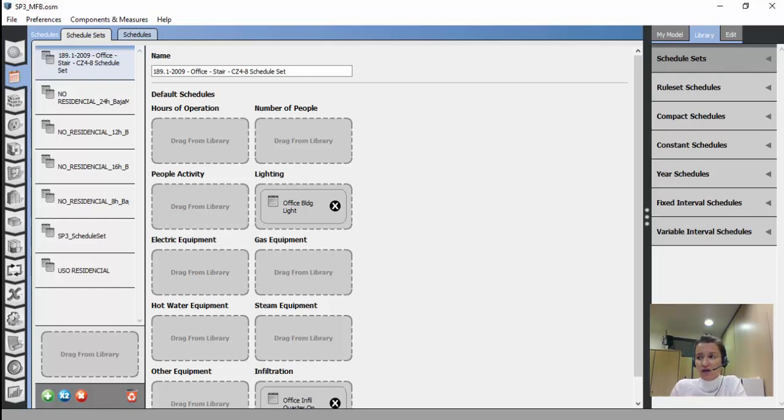This is the reason why the ePANACEA project is working on the integration of actual building energy use data, including, besides actual weather data, actual schedules and peak loads derived from the post-processing of smart meters data. For this particular case, I have already uploaded actual building data for electric equipment, lighting, and thermostat set points in order to obtain a pre-calibrated model that provides accurate results and can be used for accurate assessment of energy efficiency measures implementations.